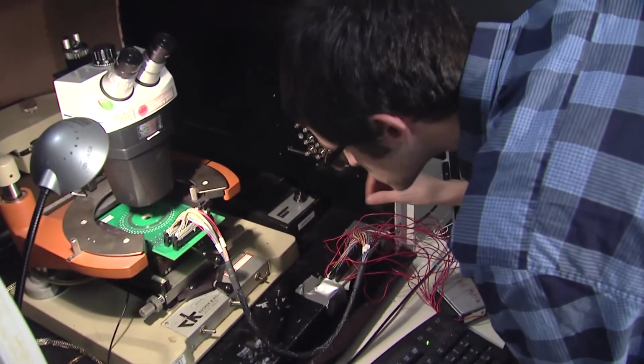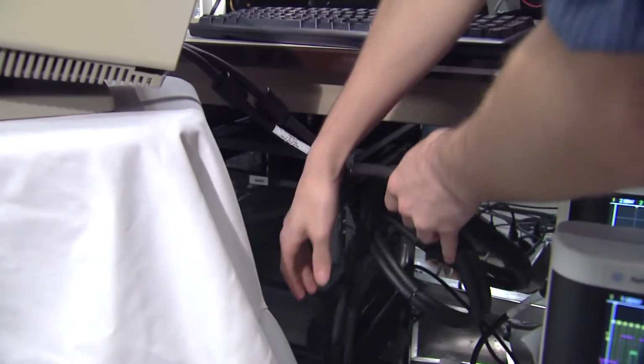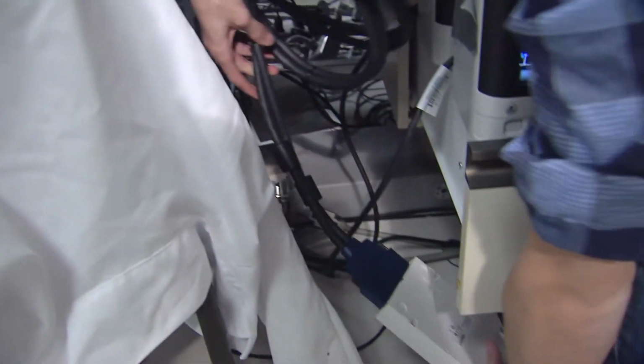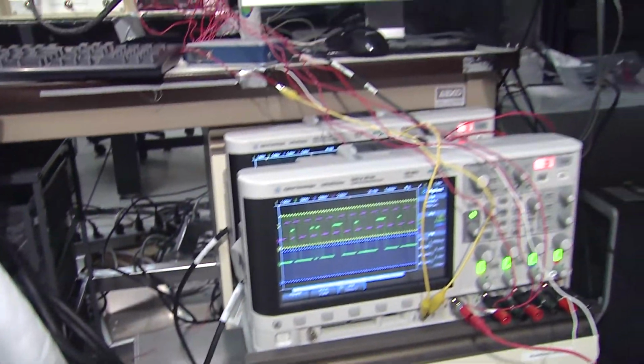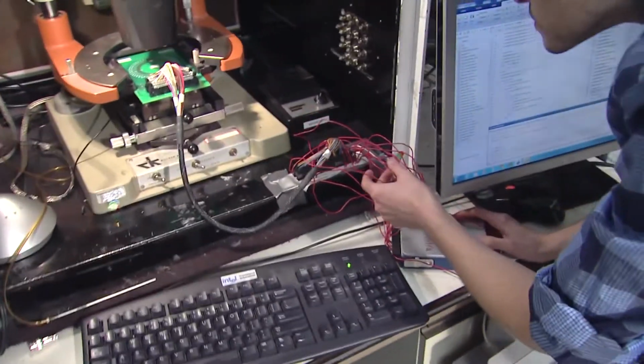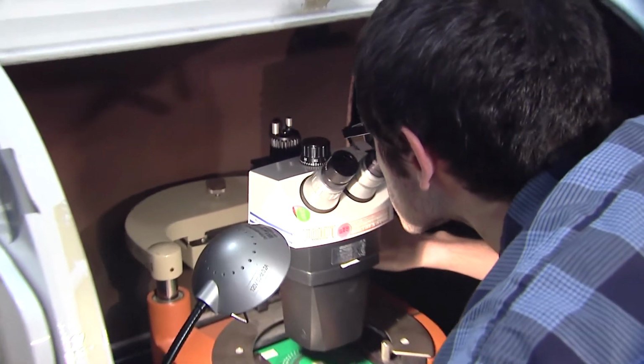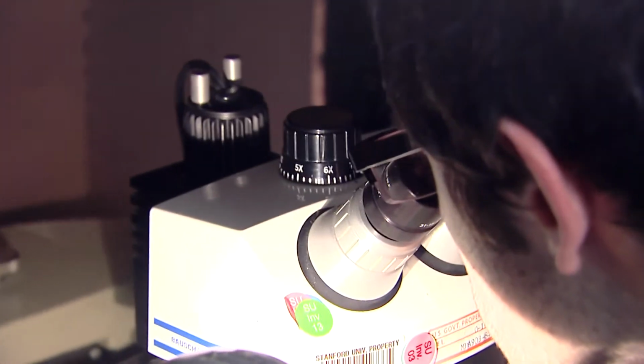Now, many of these obstacles are inherent with the carbon nanotubes themselves, such as the mispositioned and the metallic carbon nanotubes. Our group here at Stanford has come up with many techniques, some based on how we design the circuits, some based on fabrication techniques, which overcome these inherent imperfections. By overcoming these inherent imperfections, and by developing robust fabrication techniques specifically for carbon nanotubes, we're able to demonstrate for the first time some larger scale useful circuits using carbon nanotubes. Now, I'll show you 2 of the more recent circuits we've built using carbon nanotube transistors.